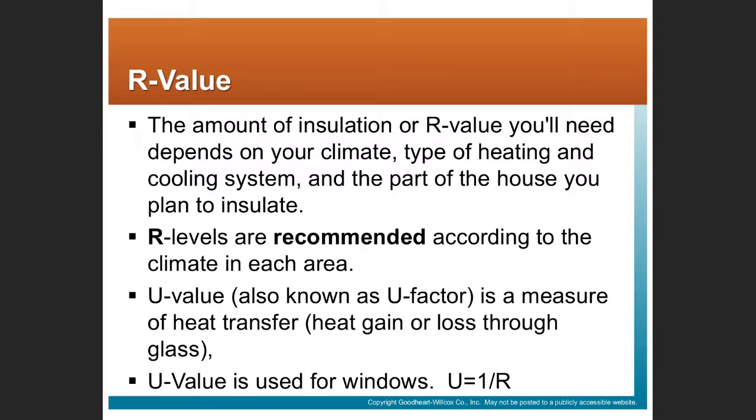Right, how much R value you need depends on your climate. It's going to depend on the building code. Nowadays, minimum R values are going to be stipulated in the building code. Remember, we talked about the building code sets minimum standards for construction.